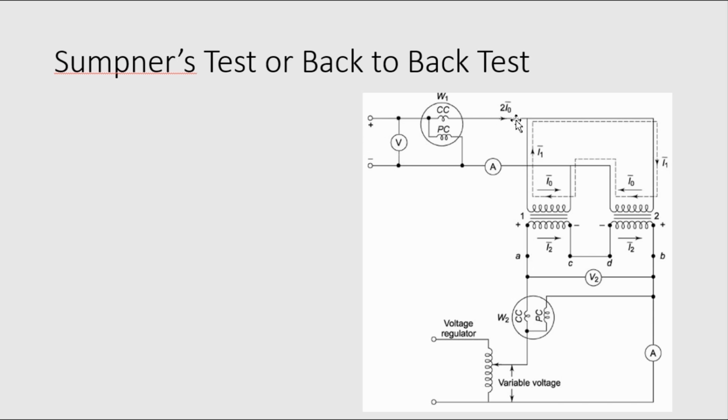So here the test is performed at rated voltage as well as rated current. So the transformer will be energized to the rated condition, the full load condition. At this stage the result will be more accurate and we can get more information about the heat. As we know the information about heat rise in the transformer winding, we can design proper insulation for the transformer.